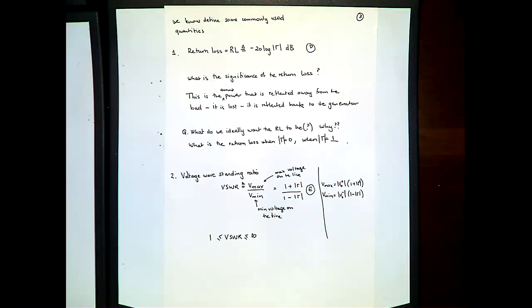And essentially what you usually say is that my antenna, because we're engineers, not mathematicians, right, is matched if the standing wave or the return loss is better than minus 10 dB. Right? That's usually an intuition that you use, because generally it's really hard to match an antenna over an extended bandwidth. So if the reflected power is such that it's accepting 90% of the power that you put on the line, then you say, well, that's good enough for engineering purposes, or for government work, the way that I'd like to say it.